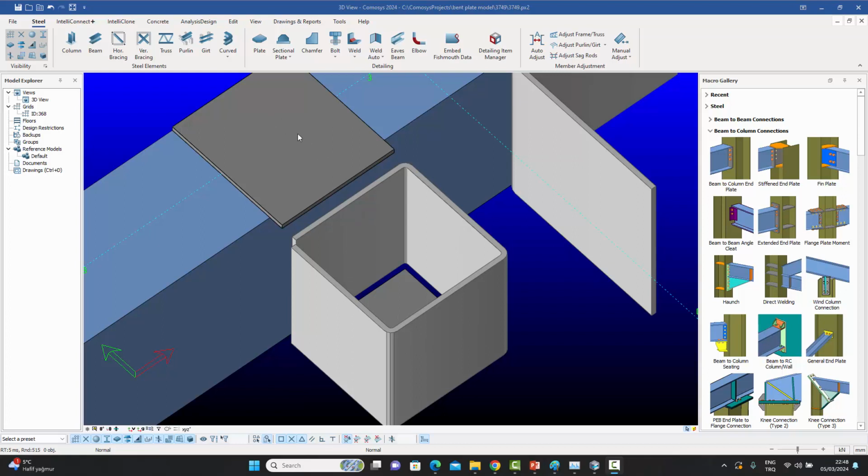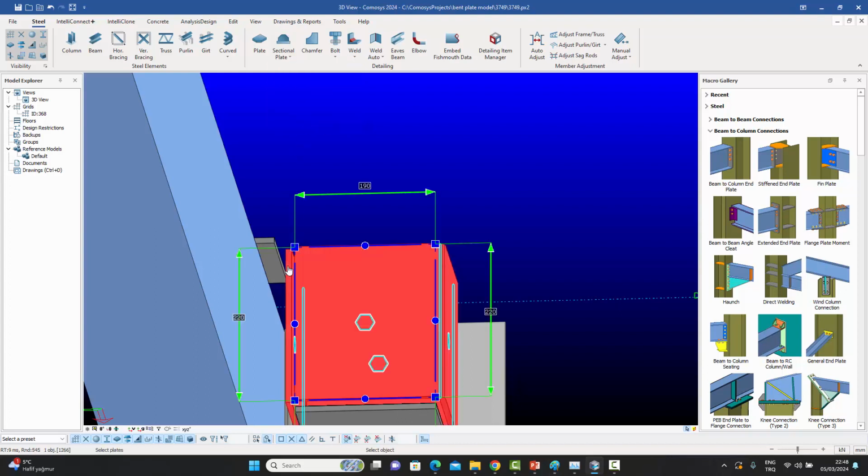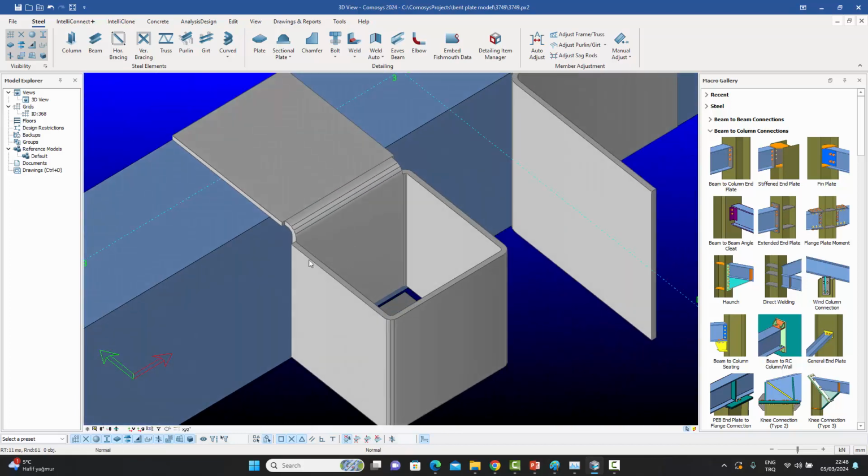But now I'm going to connect this plate to this existing plate, and this will now make it a true bent plate. So let's look at it from here. Go to my cylindrical bent plate command, choose this one, the existing bent plate, and choose the new plate. And it gives me two options at this point. I want to choose this one, which is the direct connecting one. And you can see that it has now connected this folded piece to this new plate over there.